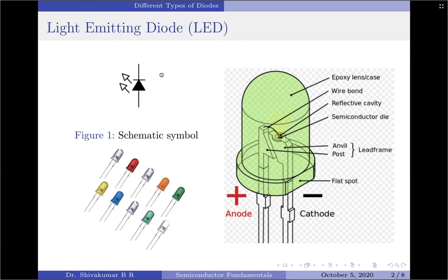The precise value of this voltage drop will depend upon the material, which in turn affects the color of the light itself. A generic red LED will likely exhibit a forward voltage drop of around 1.8 volts or so. Other colors tend to be somewhat higher as we move through the rainbow, ending with blue and ultraviolet LEDs, and also high brightness versions, up to around 3 to 4 volts.